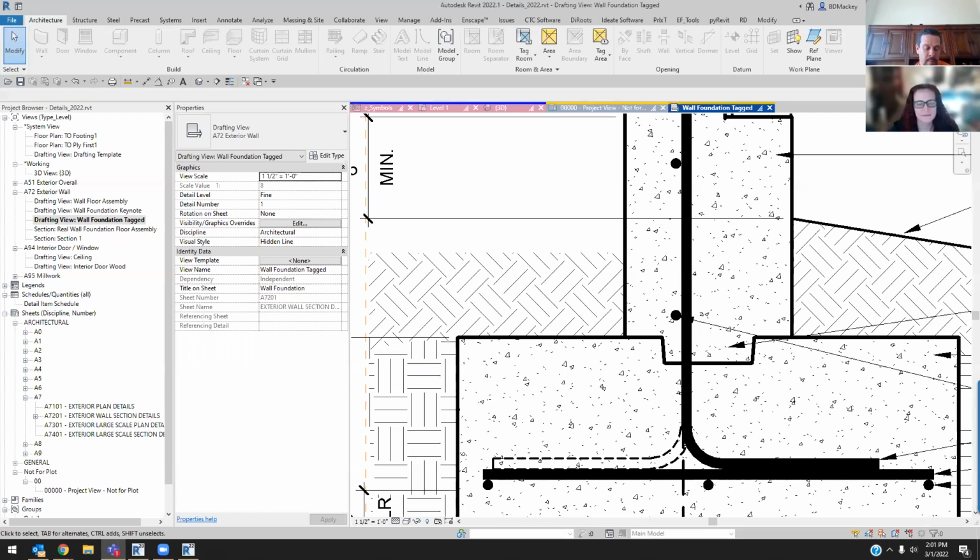But no, so for me, when I am binding, yes, there are times where I get into that bind, trying to bind that large linked model, and it just will not do it if it gets too large. If it's something that you pull off to the side that you can afford to go into, a lot of it is just start going in and delete everything that's model lines that you don't need, things like that. Like I said, it just doesn't do well on large, busy files. So if there's a lot of things in there, I use a search to find anything that's got CAD imports in it. That stuff I just delete. A lot of those things, and you see, most of the time I can eventually get the file in.